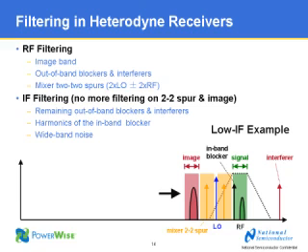So now we did the high IF example. We're going to move into the low IF example. In low IF, you will see that the LO frequency, now in the bottom right again, is moved closer to the RF band of interest. And the consequence of that, both the mixer 2-2 spur and image bands are moving closer. So the filtering becomes more and more difficult because now they're much closer. And as a consequence of that, you can see that now on the IF band, the mixer 2-2 spur and the image power level is higher, therefore reducing the sensitivity. So to get the same sensitivity you would get with a high IF example, you would need to have a much better RF filter or much better mixer. Okay.